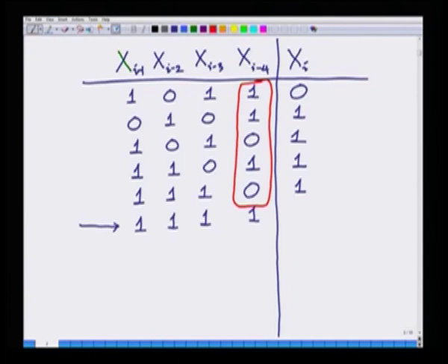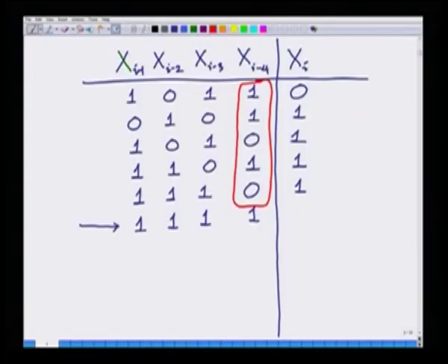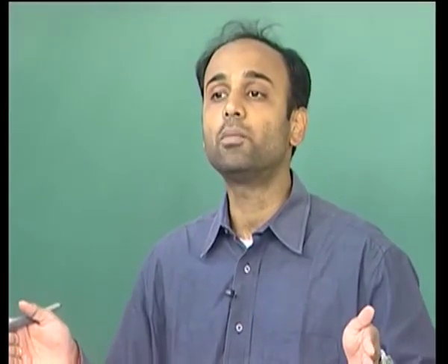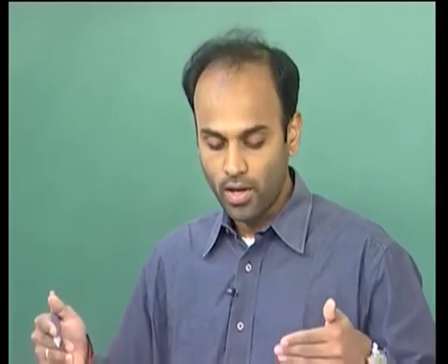That is, I am taking a single period of xi minus 4 and calling it the output sequence. Remember, this is also a pseudo noise sequence, or a PN sequence. Again, let me remind you why we want this PN sequence: because we want to generate codes that can be used for CDMA, that is, orthogonal codes that can be used amongst multiple users for multiple access.